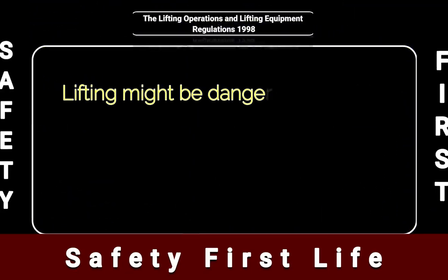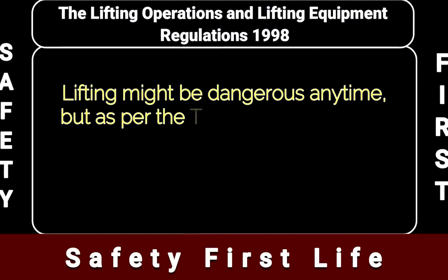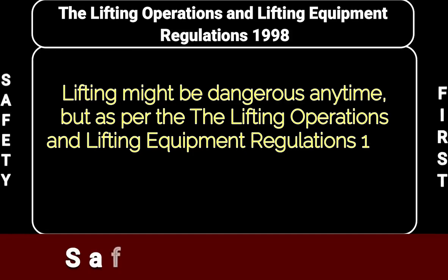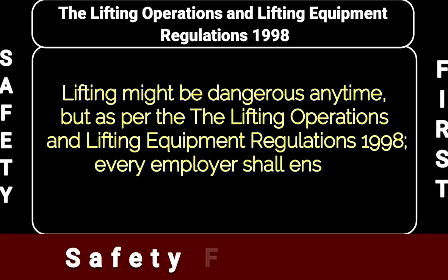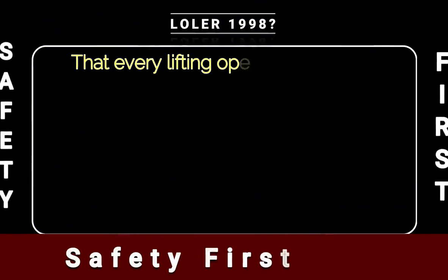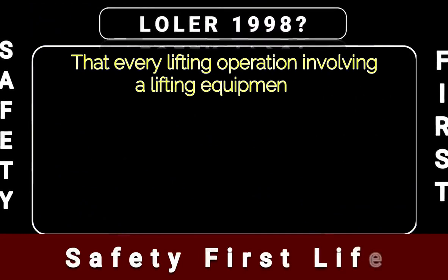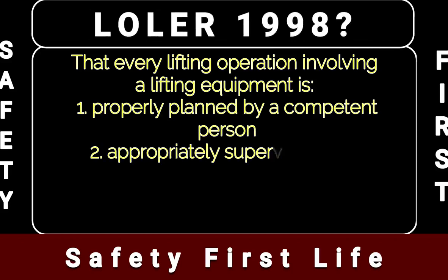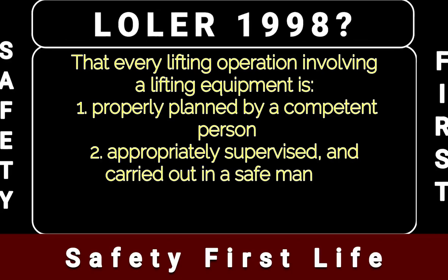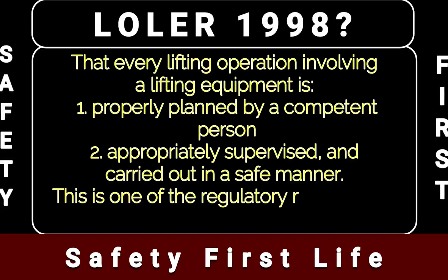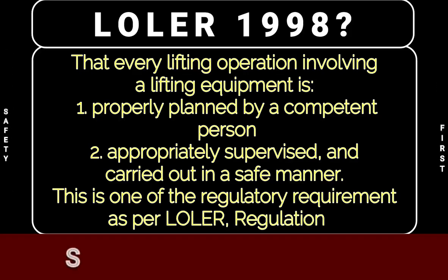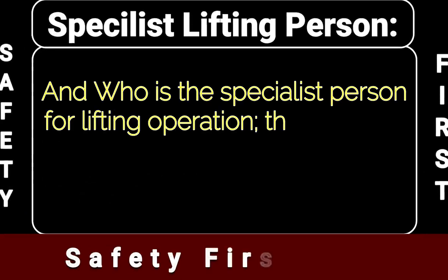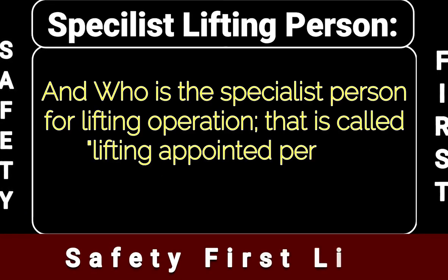Lifting might be dangerous anytime, but as per the Lifting Operations and Lifting Equipment Regulations 1998, every employer shall ensure that every lifting operation involving lifting equipment is properly planned by a competent person, appropriately supervised, and carried out in a safe manner. This is one of the regulatory requirements as per LOLER Regulation 8. And who is the specialist person for lifting operations? That is called the Lifting Appointed Person, LAP.